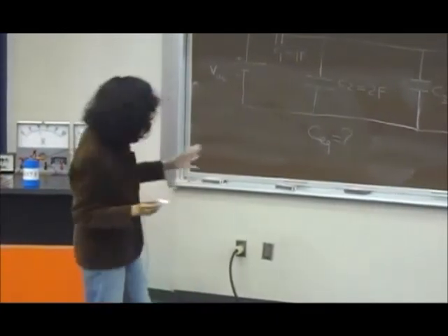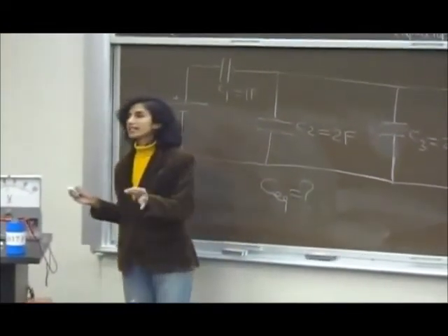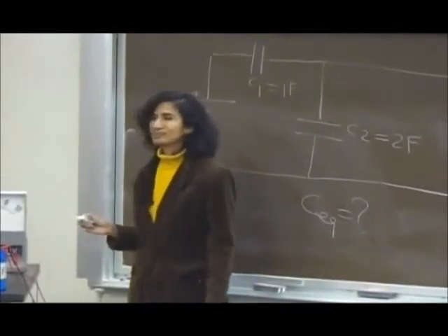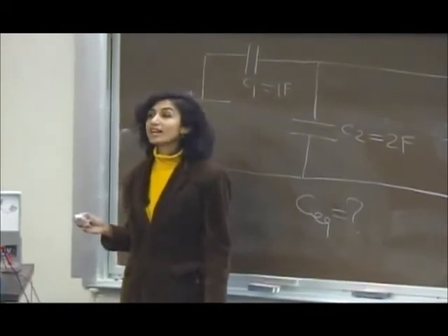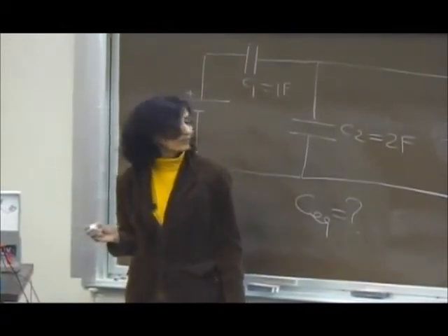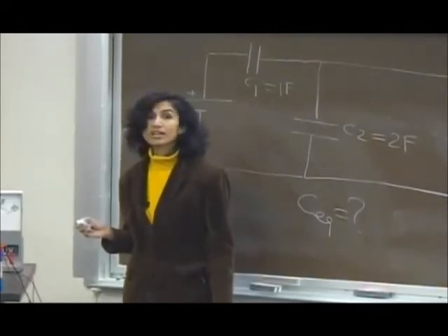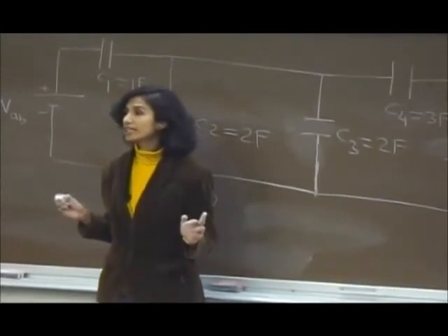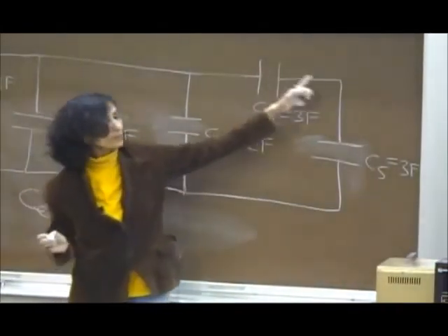So here, does anybody want to tell me that they're 100% sure two capacitors are definitely either in series or parallel? Go ahead. C4 and C5. Okay, she is saying that C4 and C5 are definitely in series? How many people agree with her that C4 and C5 are definitely in series? She's absolutely right. C4 and C5 are definitely in series. Look, there is no junction between them. Do you see that this is just one line?